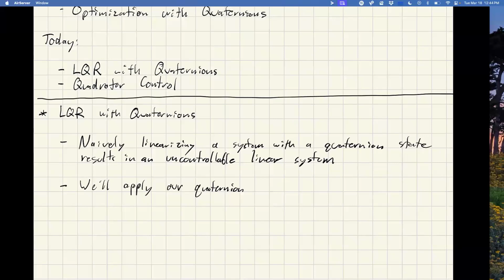Why does that thing diverge if it's uncontrollable? Think about what the cost looks like and what that integral or sum looks like. So with the cost function, I guess it vanishes. What happens over time, if the system's controllable, is the LQR controller is going to drive it to the origin. So it's going to drive the cost function to 0. So the tail is 0. And so even though you're integrating for infinite time, the integral under the curve is finite because the error converges to 0, right? If you're uncontrollable, you can't drive the error to 0. And so the cost never goes to 0. And so if you integrate for infinite time, it blows up. It doesn't converge to a constant value.